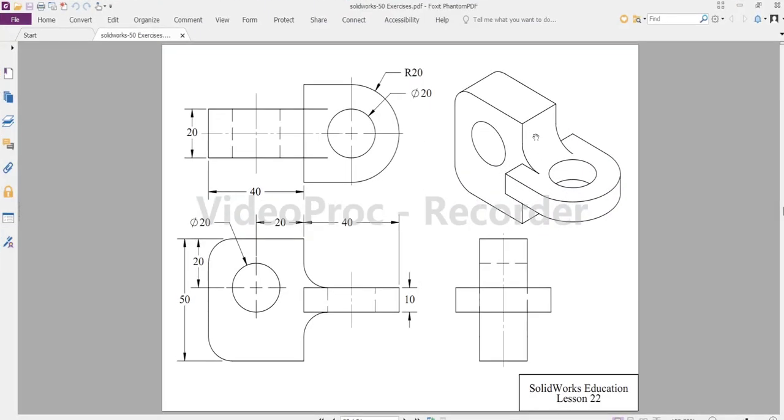So now what is remaining? Here we can see there is a fillet here and also in the downside direction. Okay, see here the front and at the top and bottom you have fillet, and again we will select fillet radius as 10.